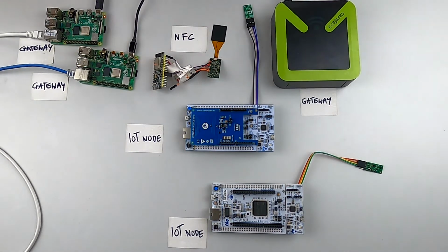Once we read the key of this microcontroller, we are taken to the onboarding tool, which allows us to set the configuration of the sensor and the gateway to which it is connected. After powering it up, we should see that the measurements are gathered by the sensor and by the gateway and are sent to the InfluxDB and UI that we have. So let's get started. First of all, I will have to read through NFC the key of the microcontroller.